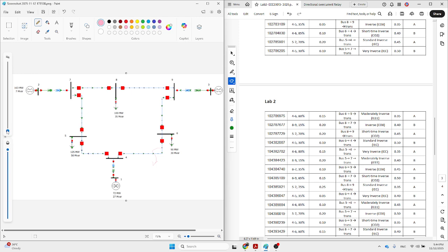The line size is not acceptable. Okay, the 4 to 6 is by here, correct? Then for our distance relay, how we should consider the distance relay location: it must be following exactly opposite of the overcurrent relay. For overcurrent relay, we're going from this one, then this one, and then the transformer. For the distance relay, we cannot see the transformer at all.